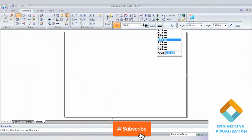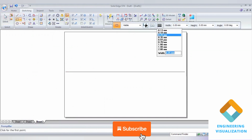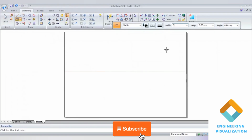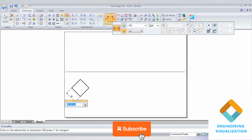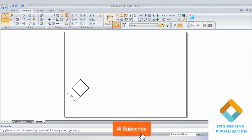Okay, first I will be constructing a square prism of dimension 30. So before that I will be drawing an XY line first. Okay, so here you can see I am drawing a square of dimension 30 and angle 45 degree. Okay, you can show the dimension for one side, you can write the namings. So we have to write the namings in small case letters.